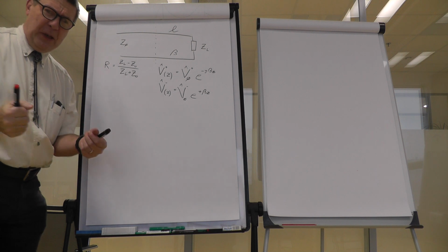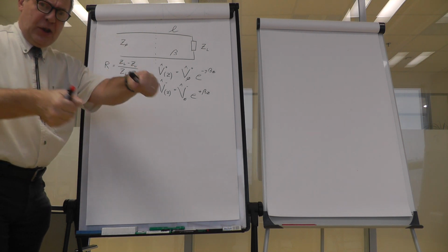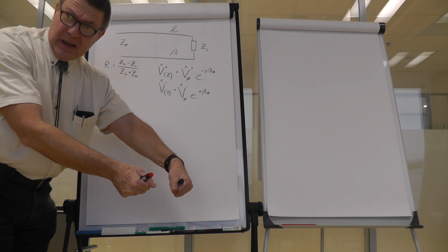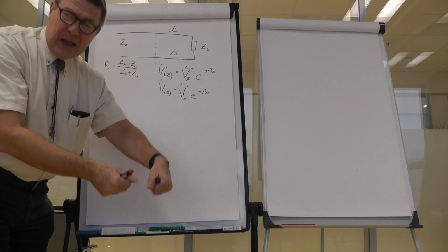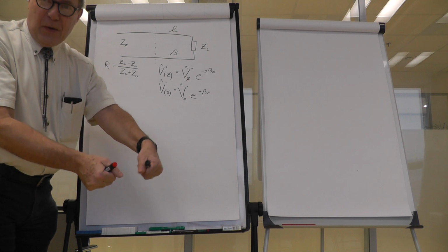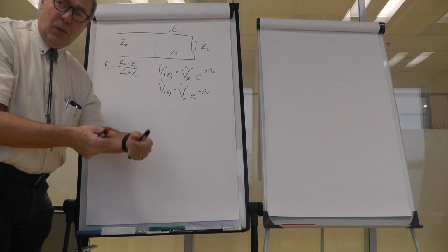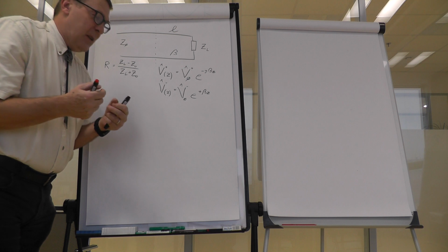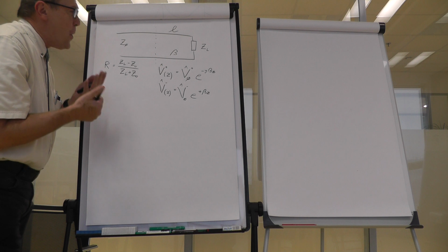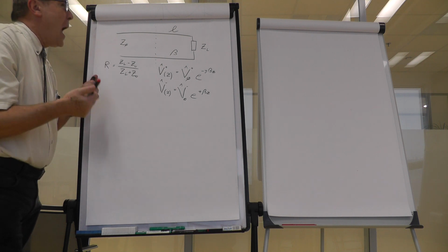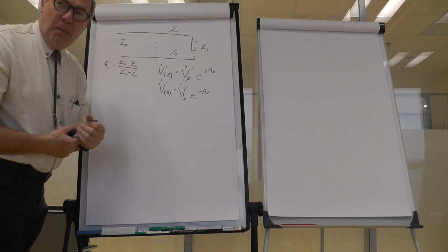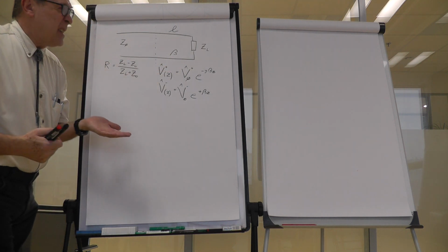We are used to having a voltmeter. We take the leads, we just put them to the resistor or transistor, and we see the voltage. This works because the frequency is very low, or the wavelength is very high, so that the length of those two wires we are using is so small that we do not count it. But if you have a transmission line, if you have the distance between the voltmeter and the load comparable to the wavelength, you would see funny things.